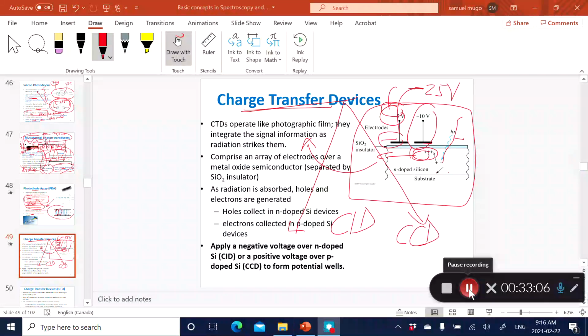Okay. So the charge coupled device is where you keep moving these holes to a charge amplifier. But as I said, you can operate it as a CID, where you're just simply measuring the voltage, the potential difference, as you move these electrons from one electrode to another.